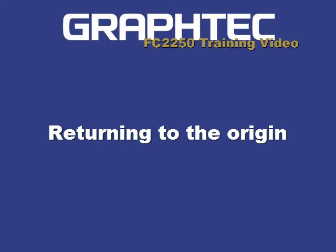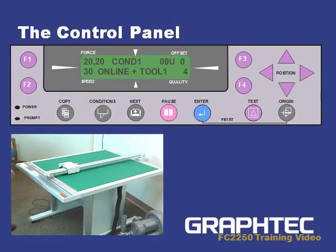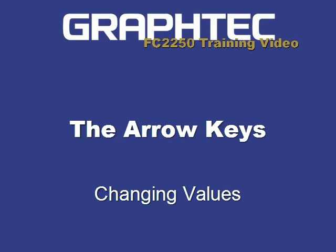Here's a little trick. Sometimes when the head is in the middle of the table and using the arrow keys to move it is a little bit too slow, you can hold down the enter and the down arrow key at the same time, and this will actually snap the head back into the lower left corner for you. The arrow keys can also be used for changing values.